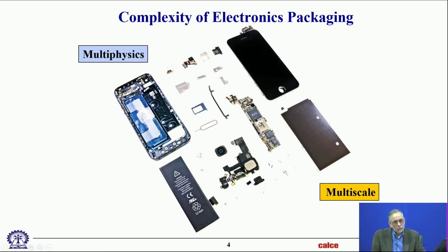A lot of people have made single molecule transistors in the lab. The question is, how do you interconnect to those? How do you build 1 billion of those on a chip, or several billions of those on a chip, with high yields? And most important, how do you package them, meaning, how do you interconnect to those? So that's the multi-scale aspect.